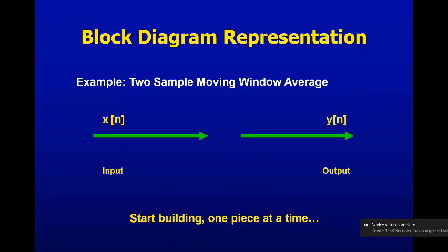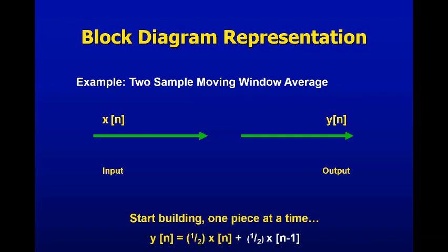And then we took that difference equation and translated it into a block diagram. It turns out all we needed were three particular components to implement a standard difference equation. We needed things that had gain, we needed things that added, we needed things that delayed.